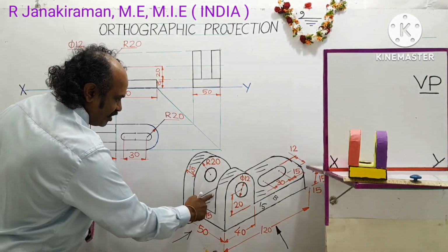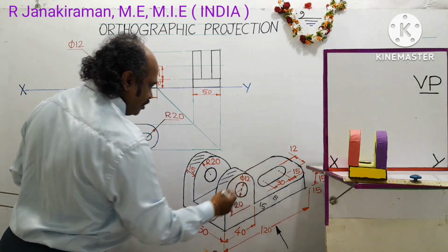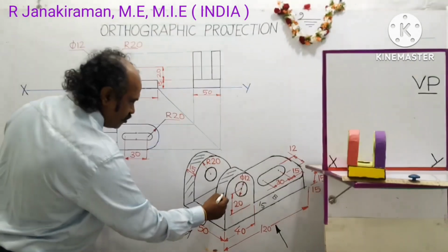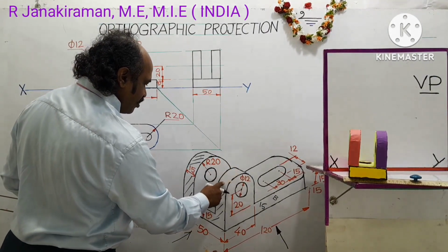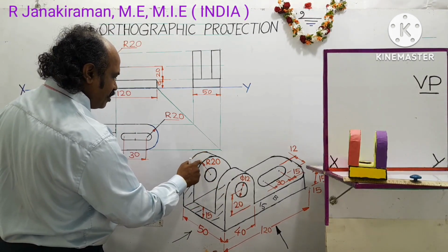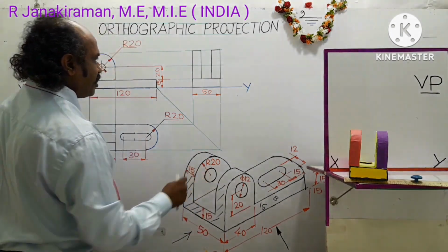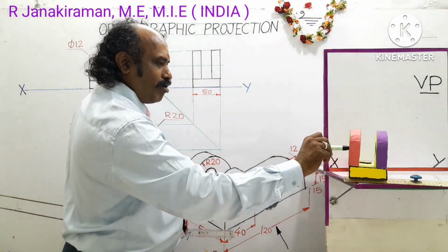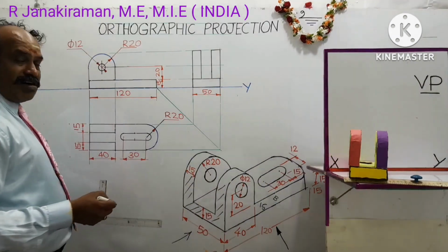So looking in this direction, the observer can see the breadth of the object. Breadth and height you can see. This will be the base part breadth, and you can see this portion. Okay. So the top surface will not be visible. The top surface we already drew in the view called the top view. Here this will be the portion visible to the observer looking from the left side of the object: base thickness and the height of the object. Okay. Looking in this direction, the viewer cannot see the hollow passage, but something is passing inside the object. That has to be shown by means of a line called a dashed line.